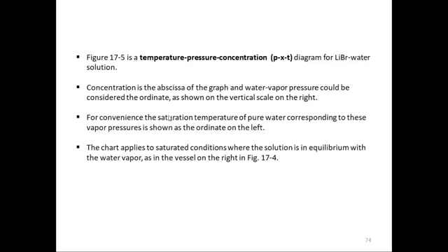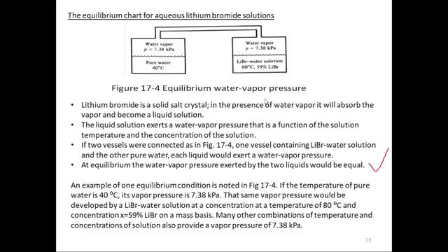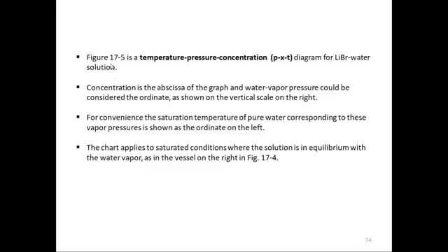And now we find out what is the concentration. Now we want to use that concentration and solution temperature to find out what is the enthalpy. So that is figure number 17-5. 17-5 is the temperature, pressure, concentration. PXT diagram, no, it's previous figure.